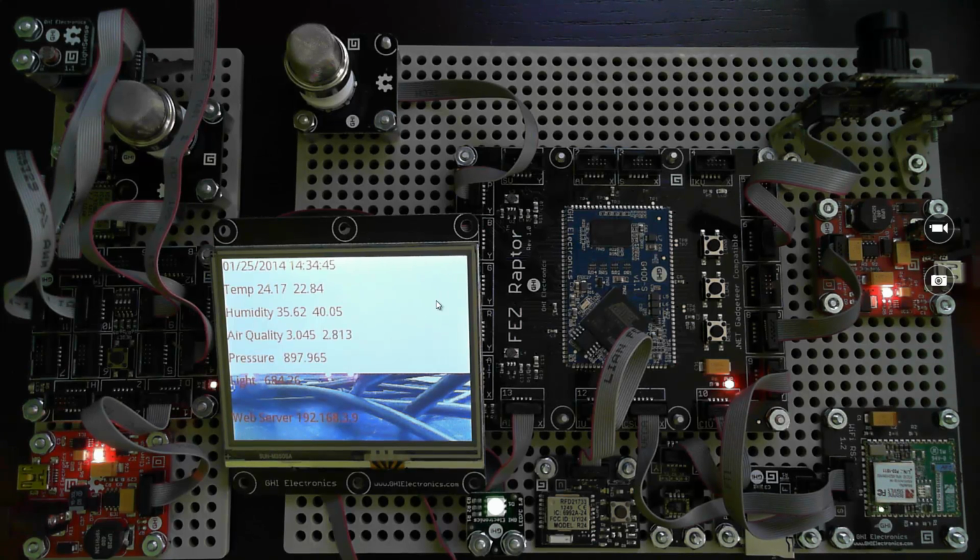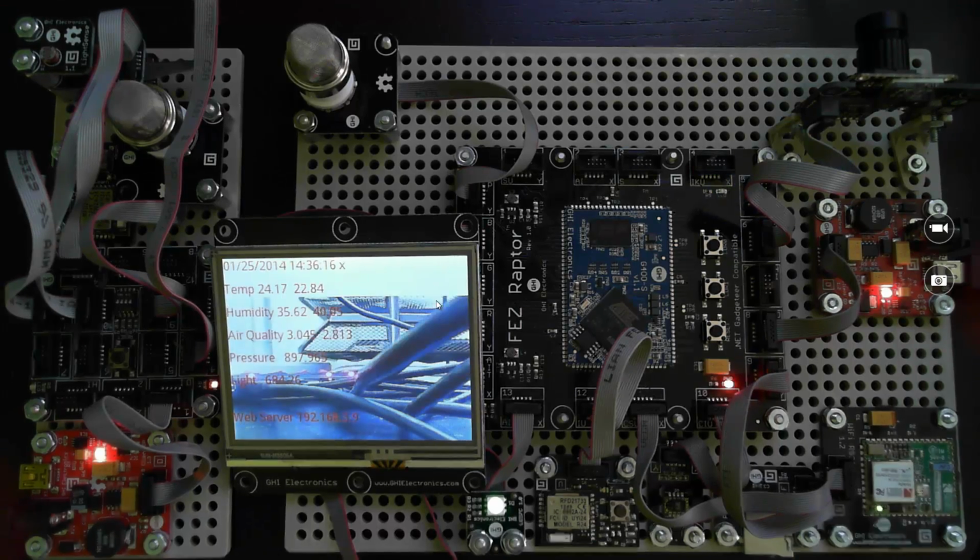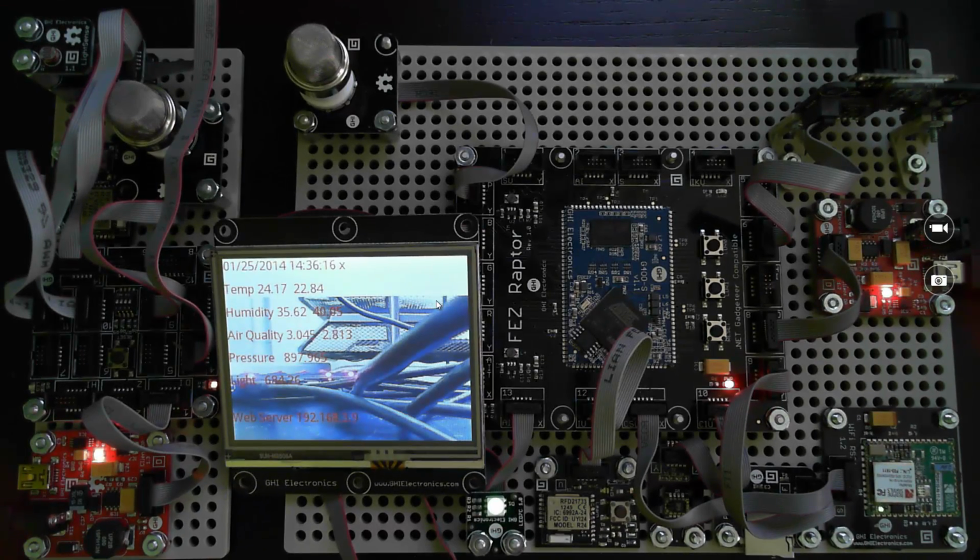It has, as I mentioned, these air quality sensors on it. They're a little bit expensive in terms of power usage, because they actually heat up a coil in order to get a reading. Looking at some of the different power management techniques, I was able to get down, say, 25% in my power consumption, which is really good, because when it comes to battery devices, power is king,